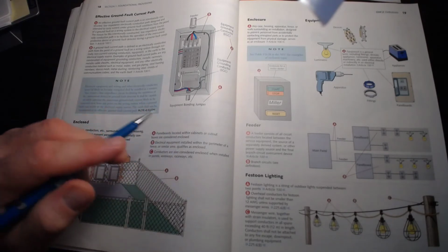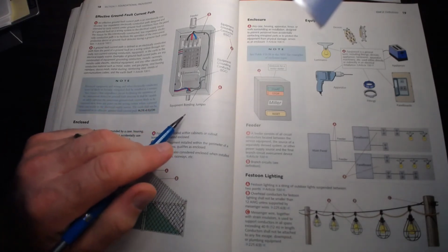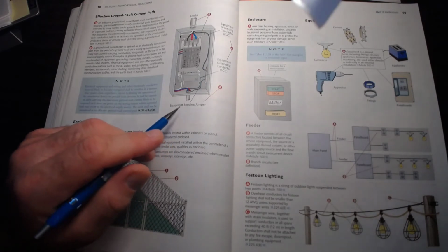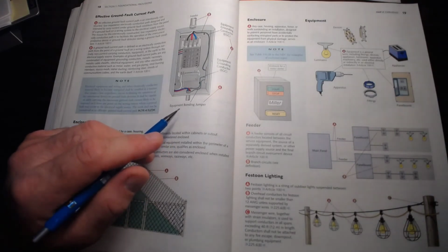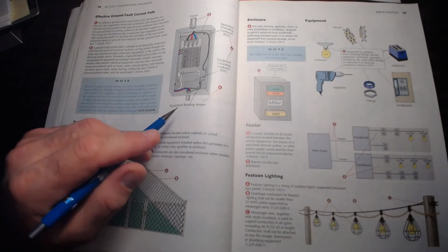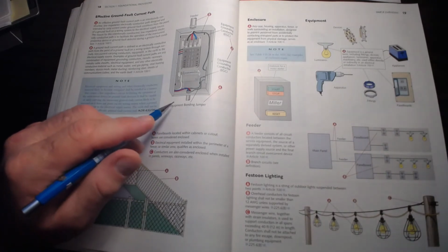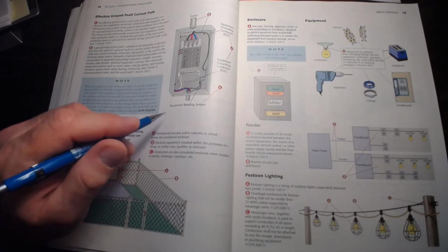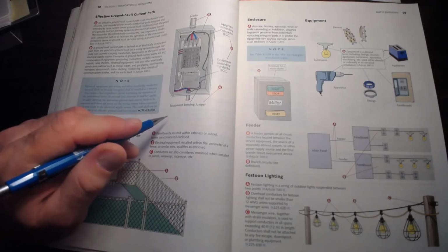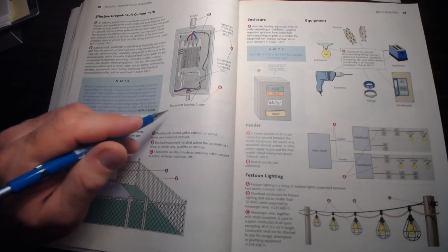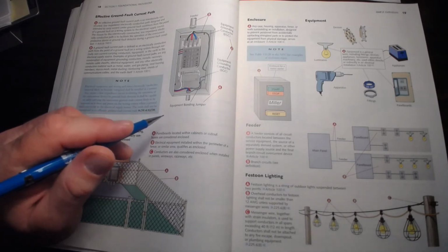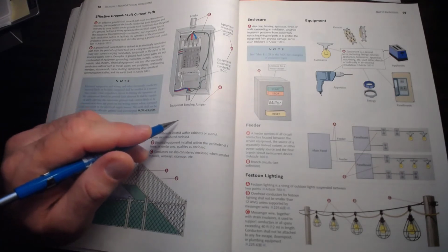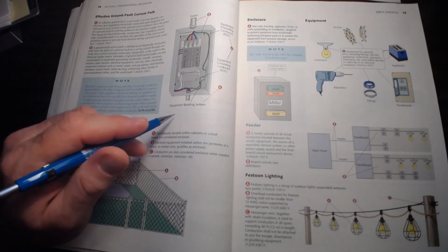I had an issue I was working on up in the mountains, and our problem was because the ground was decomposed granite, and that decomposed granite with no water in it, no moisture in the soil, is a resistor, not a conductor. So if we have very dry sand, again, the same thing. It's not a conductor anymore. It's a resistor. And so the transformer supplying this will just make it look like load.